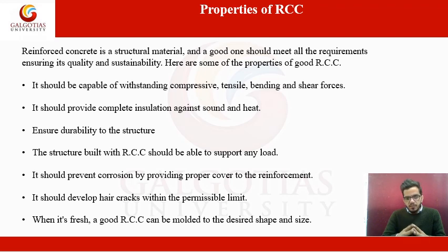It should ensure durability to the structure. The structure built with RCC, which is called the RCC frame structure, should be able to support any kind of load, the dead load and the live load. It should prevent corrosion by providing proper cover to the reinforcement. The concrete used in reinforced cement concrete should provide a proper cover to the reinforcement to avoid corrosion of the steel.